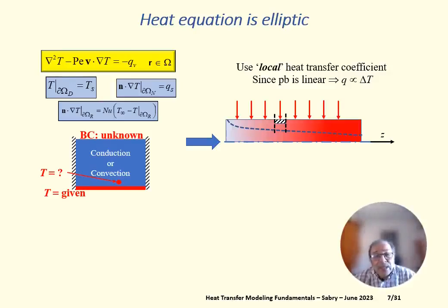Should I say H is 0 at that point? Maybe. But in this case, we will normally ask the question, why do I have delta T if I don't have heat? That's why Robert Moffat has invented a concept he named the adiabatic heat transfer coefficient. I'm not using this concept, but at least it explains to us that the local assumption is not a good assumption.